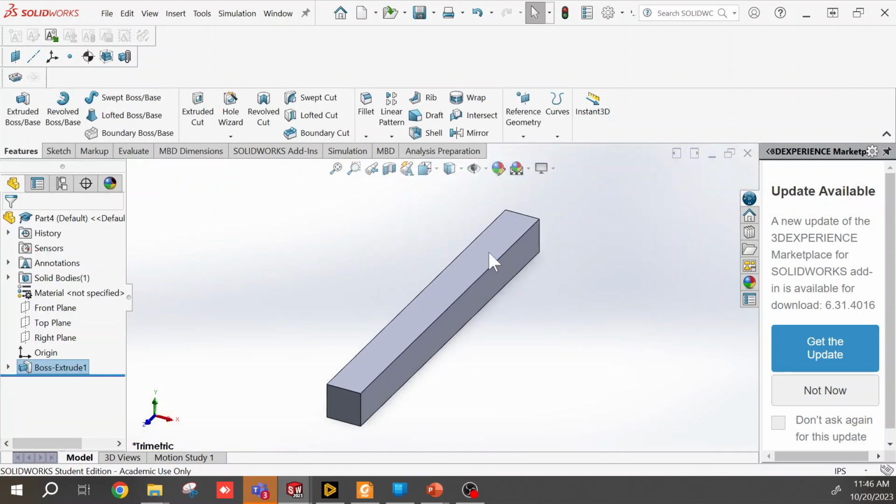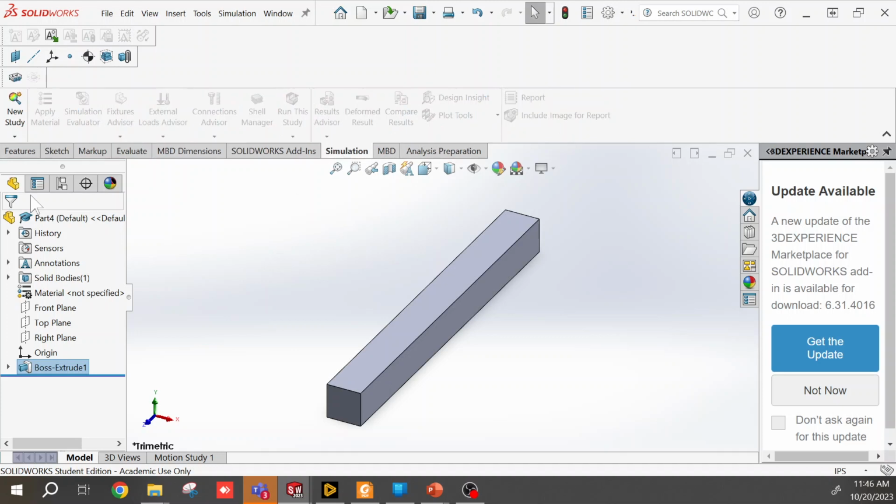Sorry for going through that really quick, but it's not really the focus of this particular talk. Everyone should be able to get to that stage really easily. So once you have a geometry, it's as simple as creating a study by going to the simulation tab here and going new study. So left click, new study.